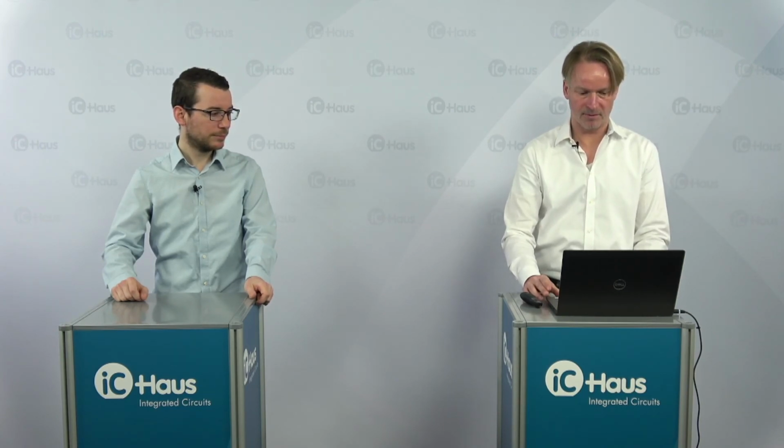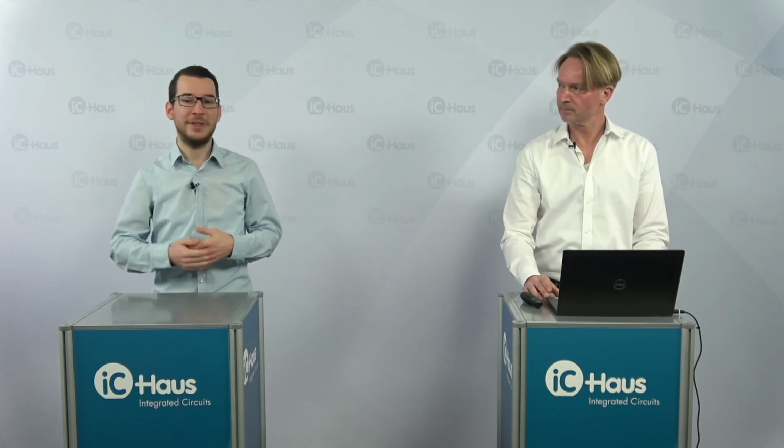Okay, thank you. Next question: what is the turnaround time difference between BiSS C 6-wire and BiSS Line, meaning starting the request in the BiSS C master until data is available in the BiSS master? I'm not quite sure about the question. So I think it's about the delay between the BiSS Line slave and the BiSS C communication. The BiSS Line slave, or iC-BL, works with an internal system clock frequency of 100 megahertz. So the delay of iC-BL is quite low, but it depends, of course, on the connected sensor and its sampling frequency when it is about to start.